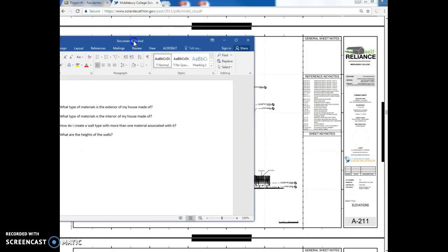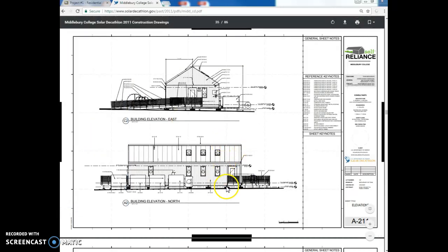So what we need to do is, again, take a look at our drawing set, and we can look at these elevations and sections, and we can see the different levels. There are datum lines in here. This says grade level, this says top of finished floor, the bottom of the roof header. There are different datum lines, so you are going to want to recreate these datum lines in your elevation drawings.